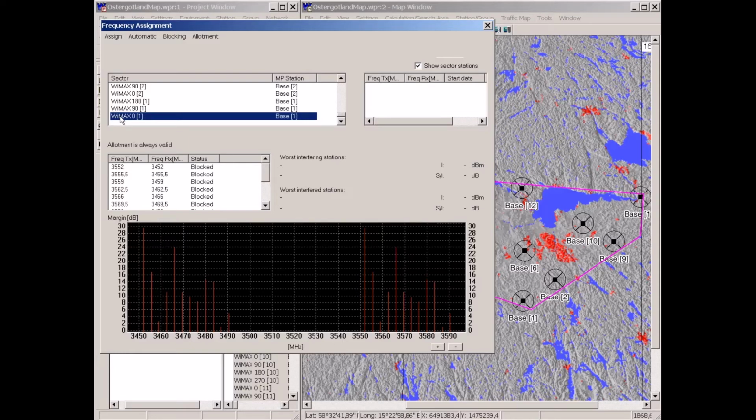Okay, here it can be seen that all the colors are red on this, but we can also see that it is only at about 1 dB above the assignable threshold. And we can see here we achieved 19 dB. The requirement for the receivers has been defined to be 20 dB. So if we assign that, it will work quite well. We have only 1 dB of interference, so that's not a big deal.